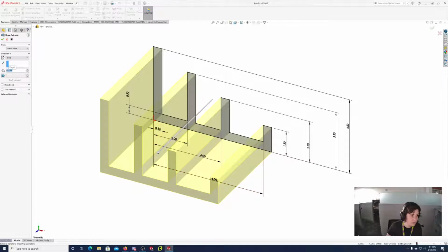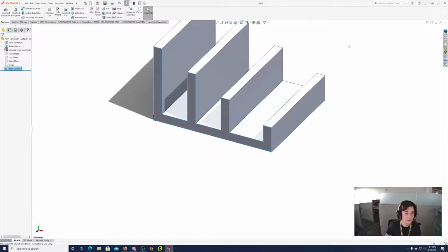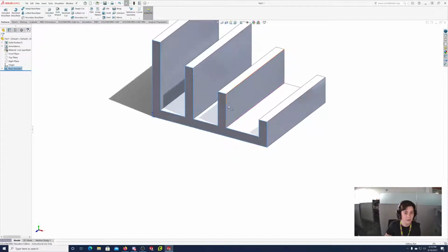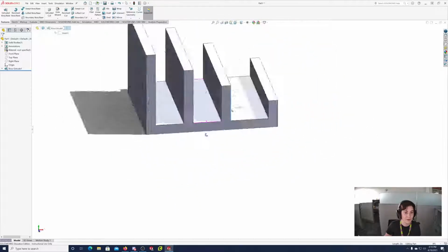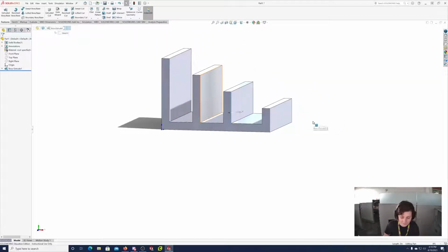We do want to enable the reverse direction, so we want it going away from us, from the sketch. So click those 2 arrows there. And then we're going to click OK. And now we have a 3-dimensional little set of stairs or something. I don't know. Not really stairs, but it's a 3-dimensional shape. So pretty cool. Is everyone with me there?